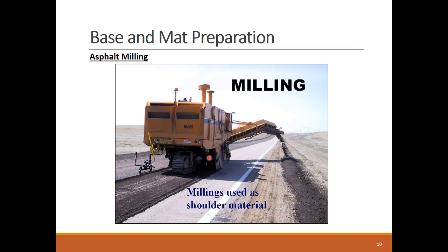The retrieved asphalt milling can be recycled on-site by placing it on the shoulder strip along the road. This milling windrow is spread and compacted afterwards to provide a leveled shoulder surface.